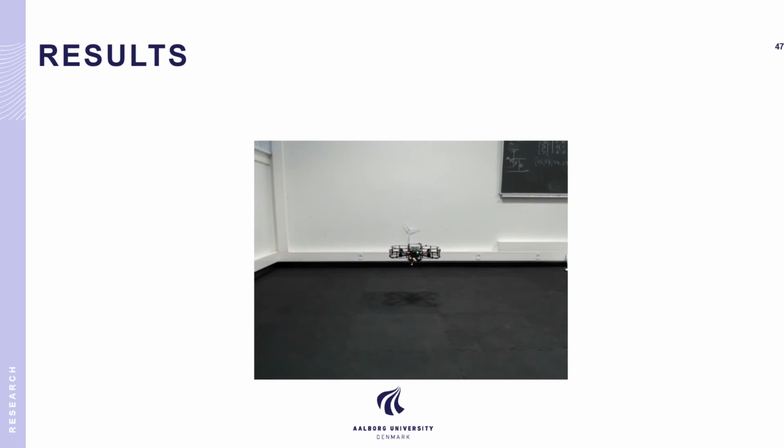When the drone stops, it starts navigating towards the wind turbine using the visual input both for collision avoidance and for yaw movement. You can see here it's actually moving forward and controlling yaw based on visual input. So there's no operator at this point. This is purely based on the segmented visual input and neural network calculations.